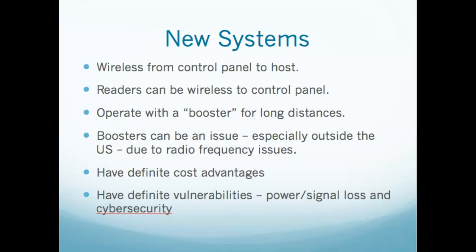But outside the U.S., there are problems with wireless boosters. I bring this up only because I tried to do it in Stockholm about a year or so ago. I was going to do everything wireless because it was a cheaper way than running all the wire, and got shut down because the radio frequency to operate the wireless was one that was already in use, and there was not one available. By law, they regulate which frequencies you can use, and I didn't have one available, so it was a non-starter. There are definite cost advantages to wireless, because running wiring costs a lot more money, and wires break.